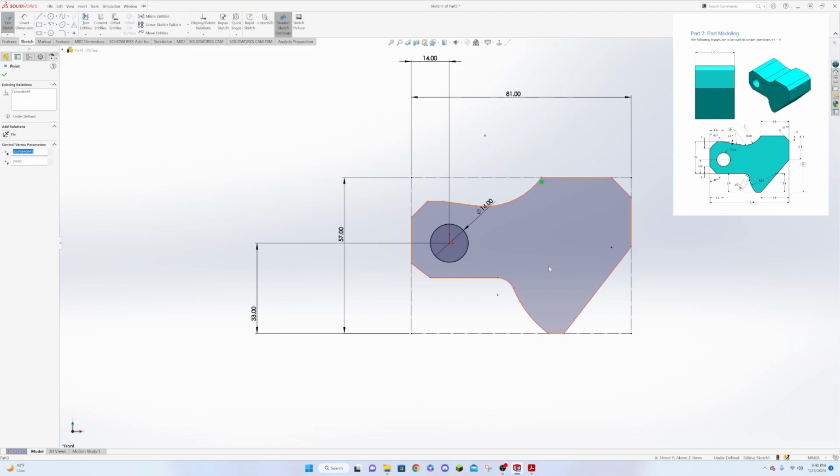Okay, so one of the first ones that we already have defined is, and you can see that it's already snapped black because it's sitting on this line. Any of the lines that are sitting on our construction lines already have a black shade to them because at least one of their relationships is known. They're coincident with this line. So they don't know where they start and stop, but they know they're on this line. So that's good. That's going to drive part of what our drawing looks like.